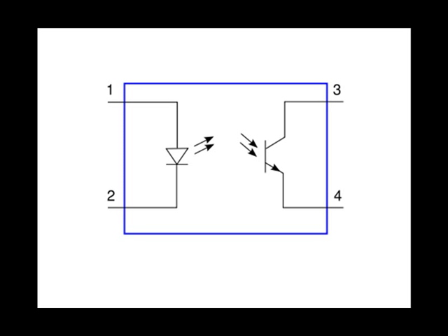Lower isolation ratings are acceptable for devices that don't use high voltage. Typically, these solid-state relays are limited to switching 240 volts AC or less. Let's add a few more components to the diagram to illustrate a more complete circuit.